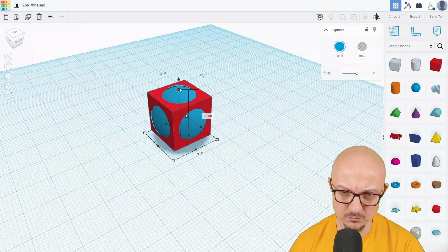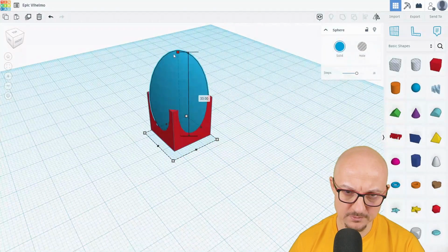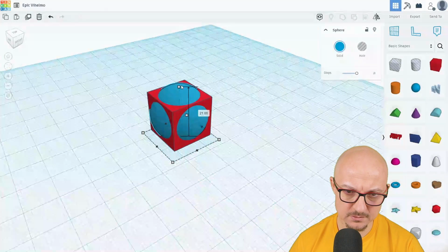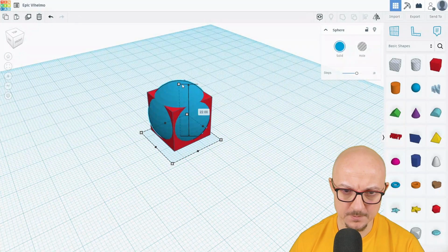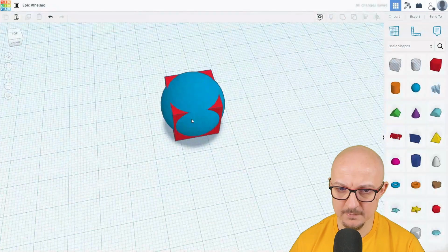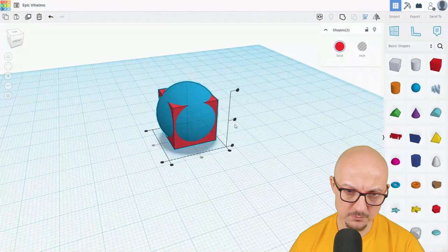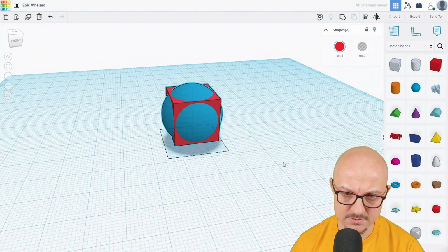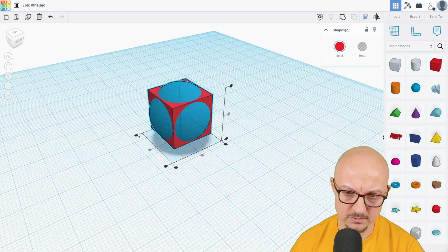But we know from learnings before that the sphere is a bit too small. So we can change the size of it, but you see what's happening? We are creating an egg. If we press the shift button, it will resize in all 3 dimensions, and we know it should be 22, but as you can see, it's not aligned again. So we select both, press L for align, and we need to align in the Z-axis. And yeah, it's aligned now. And now intersection.